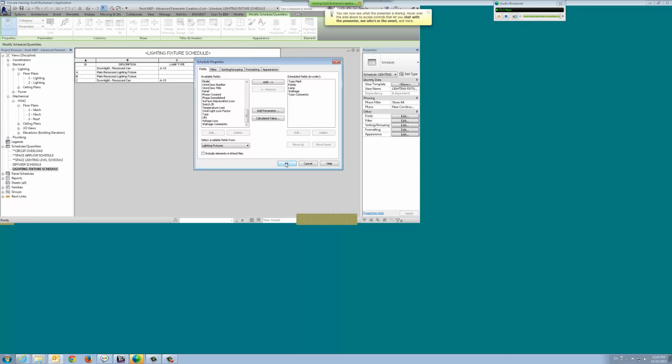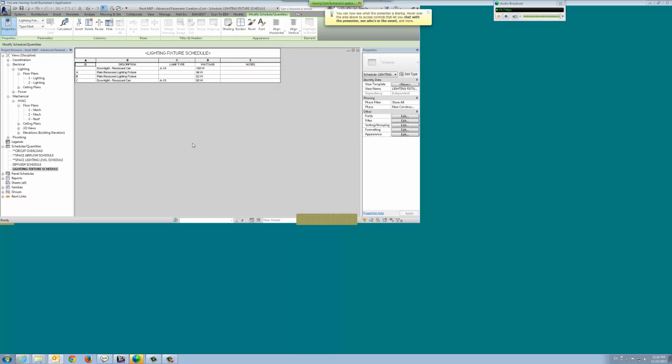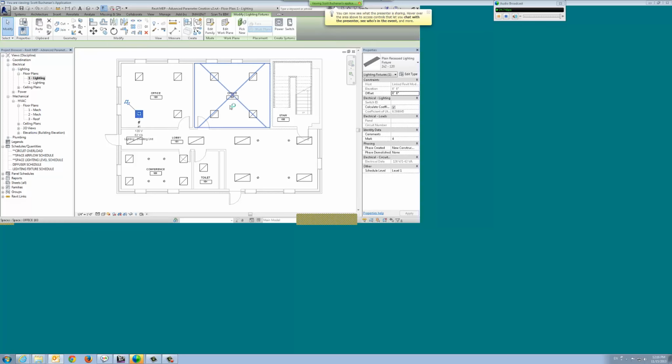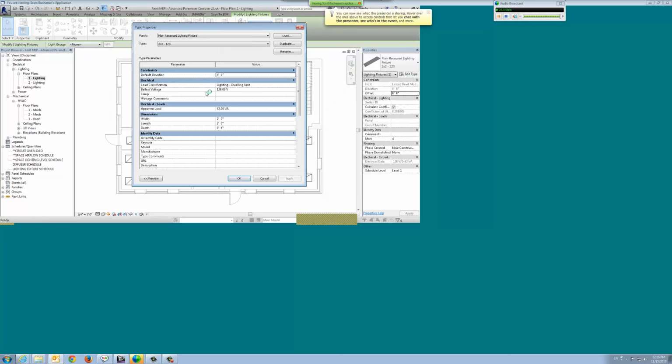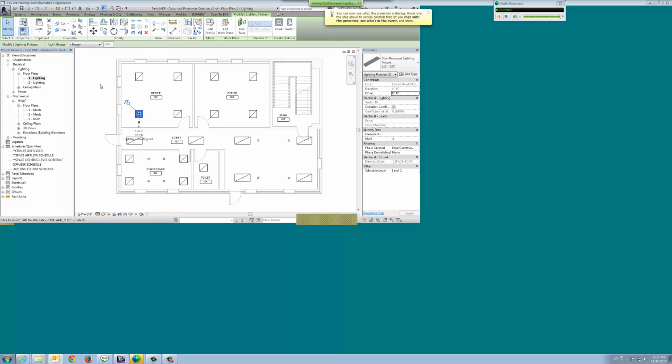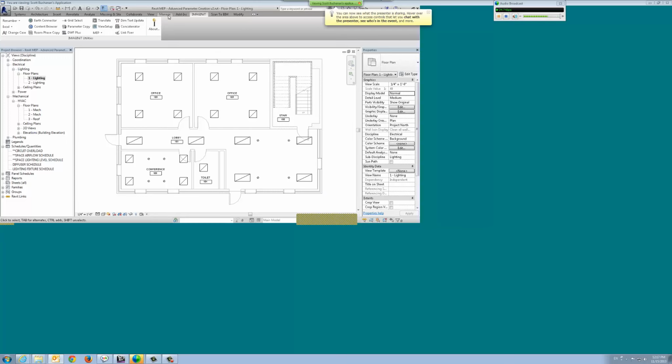So what I'm going to do is create myself a project parameter. That way, I can pull information from the object and populate that project parameter, and that can be the one that I end up scheduling. Because if we go to the actual project and look at one of these lights, we know voltage is on that object. When an electrical connector is placed in a family, we've got this ballast voltage parameter that appears. Right there it is. But again, it's just one of those tricky parameters you can't get to right out of the box with the software. So we're going to create basically a portal for this to come across for us. And again, this is just a workaround if you don't have your library all the way completed with standard parameters.